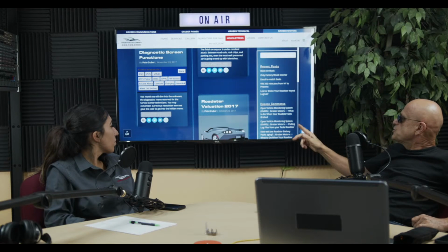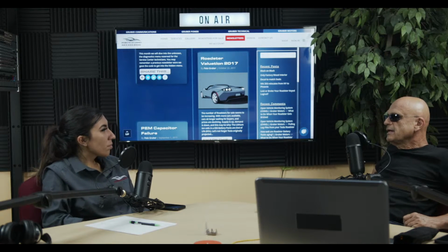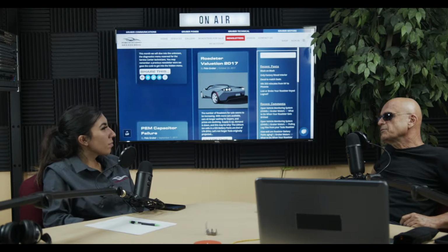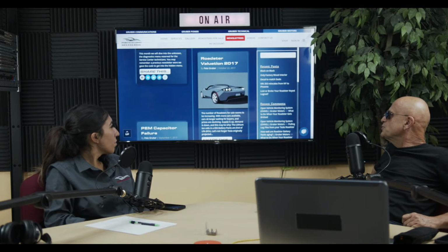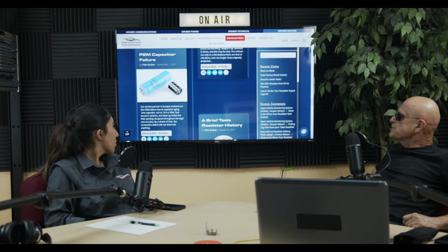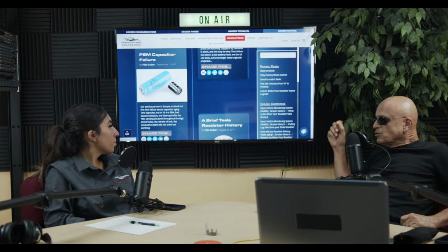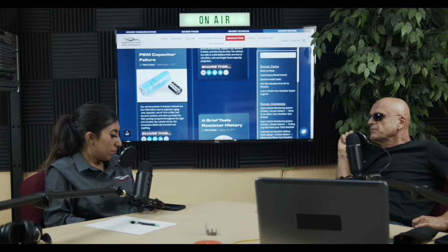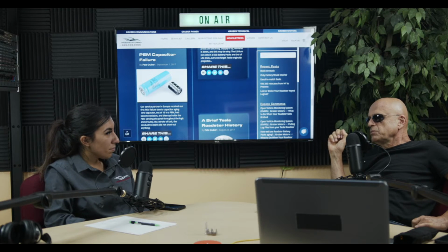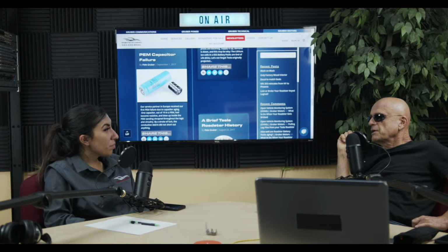There was an early valuation newsletter that we did in 2017. Of course, that all changed by the time we did the next one in 2019. And it's exciting to see that Roadsters are continuing to climb in value and what will happen over the next few years. The PEM Capacitor Failure newsletter actually has pictures of the European Roadster where the capacitor blew up, and you can see the carnage inside that PEM. I don't know how it happened, but the gods were smiling that day. All that conductive shrapnel that was blown throughout the PEM, none of it appeared to have shorted anything or affected anything in the PEM, and our European counterpart was able to rebuild this PEM. Oh, that's good.